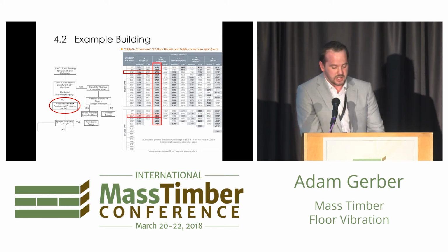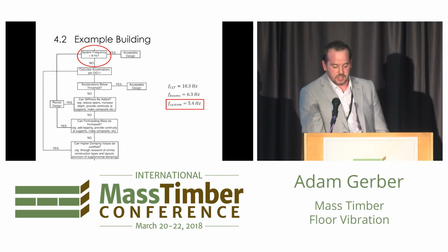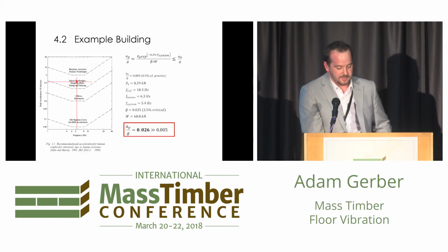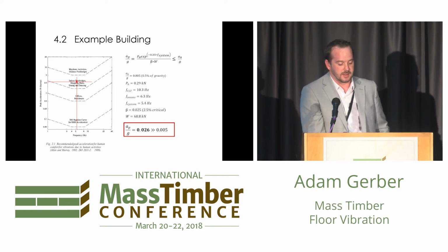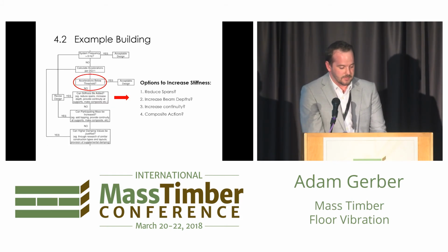And so when we go through and we check the frequency, our CLT panel frequency is about just over 10 hertz. So we'd be pretty comfortable with that if it was well-supported. But the beams themselves were at about 6 hertz, and the combined frequency is 5.5 or so. So that doesn't necessarily mean that it doesn't work. It just means you need to go into a little bit more detail and verify the accelerations. So if we do that, we're at just about 2.5%, which is about 5 times the acceptable limit. So we know we have a problem to deal with.